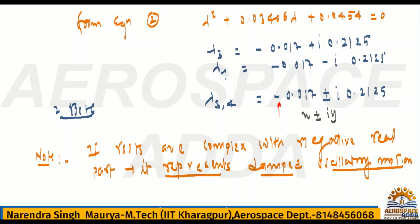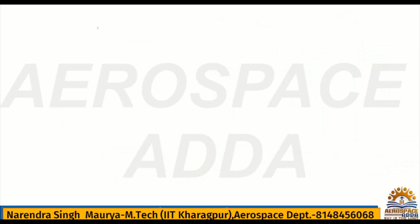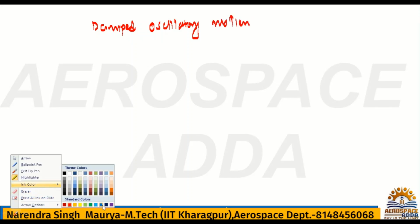I'll write it here: damped oscillatory motion is minus chi omega n plus minus i in bracket square root of 1 minus chi square, into omega n.